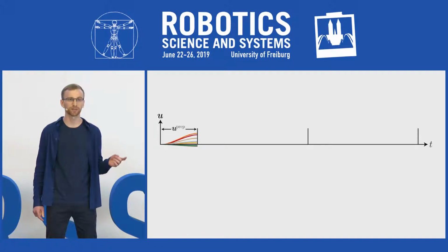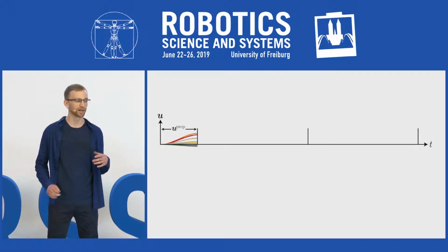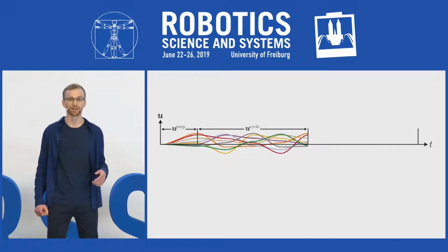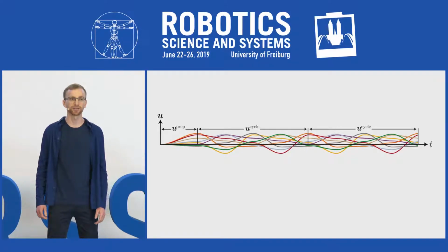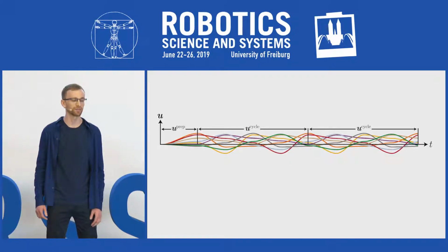It begins with a preparatory phase that moves the robot from rest and into a cyclic phase, where the robot actually walks. We include 2 copies of this cyclic phase to ensure we find a conservative strategy for motion that continues to make progress after the first walk cycle. The entire trajectory is parameterized with splines.